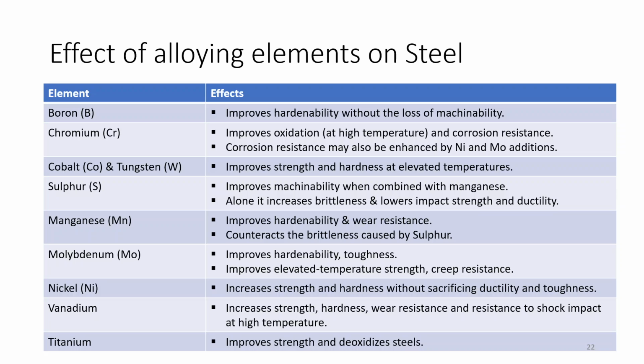Okay, so nickel and iron are sitting very close in the periodic table. When you add nickel, it will just replace iron and won't produce as much lattice mismatch compared to other elements that you're adding.